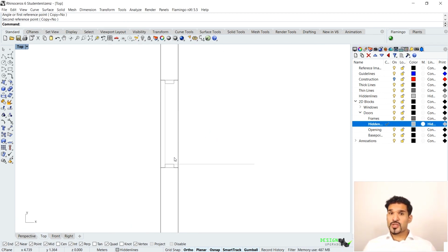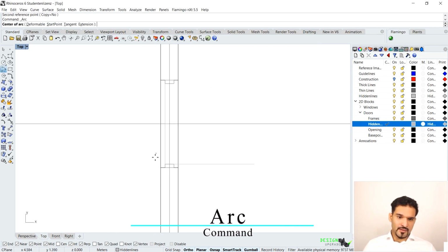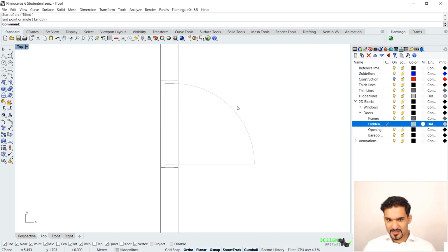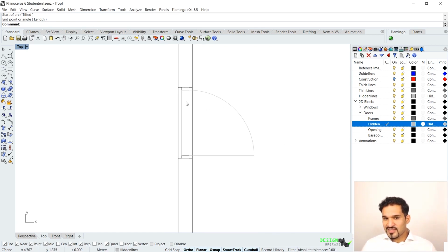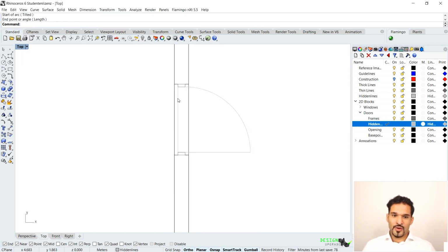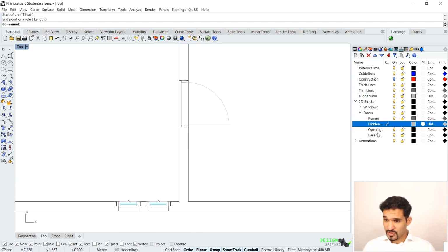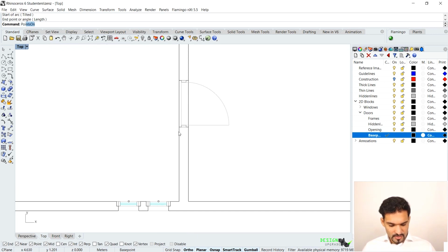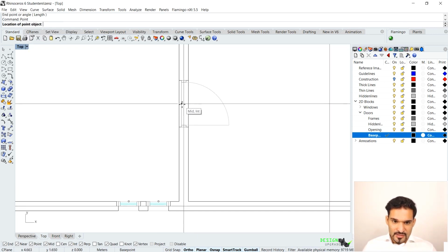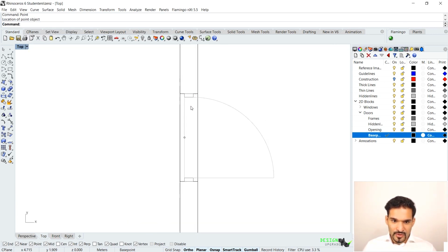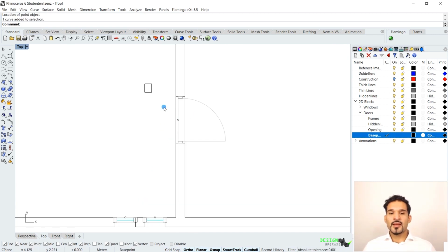And what I also want to do is create an arc. This is basically the door swing, which has been displayed like so. Now, actually, this is it. This is my door. If I want, I can also just keep that now and just add a point. So I go to my base point, this point, and define my middle here on this line, on the middle line of this middle point. Select that.